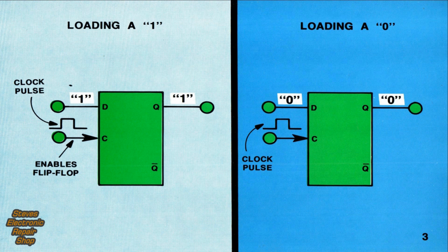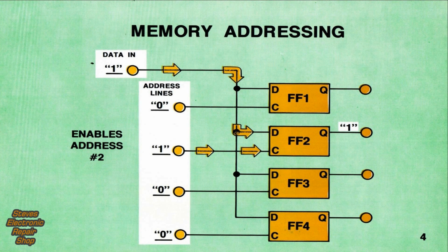Of course, the basic flip-flop can only store 1 bit. To be a practical memory, many such flip-flops are required. Storage capacity can be expanded by paralleling flip-flops, as shown here. This array contains 4 storage elements and therefore can store 4 bits. Notice that the D inputs are tied together. Also, address lines shown on the left allow discrete selection of each flip-flop.